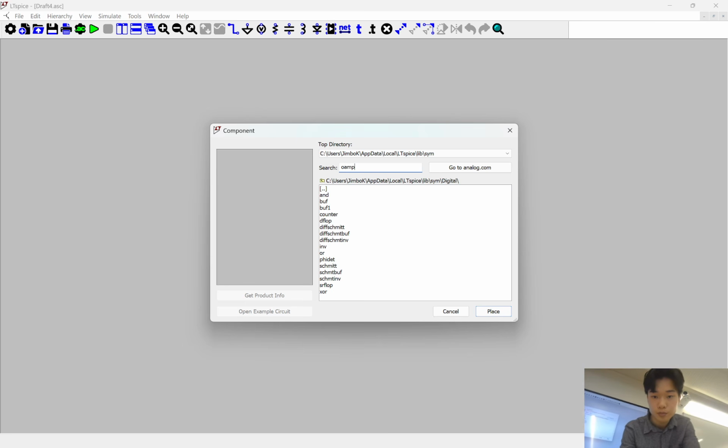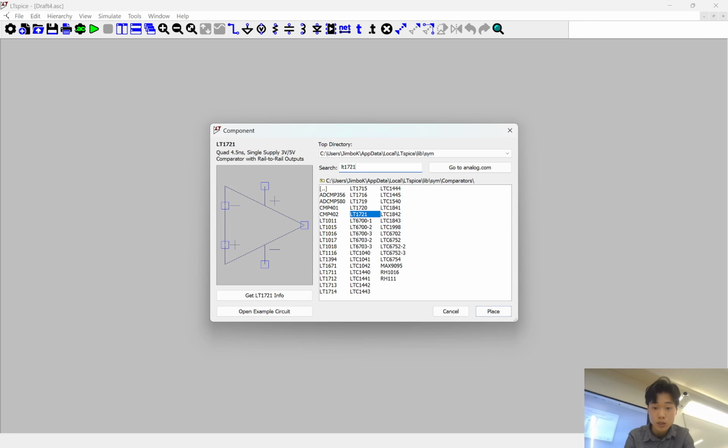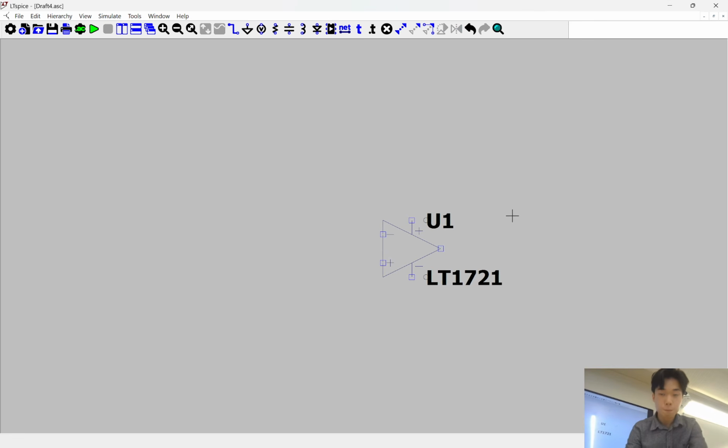So in the notes, we've listed LT1721, right? It's just some op-amp model. I guess it just depends on the application, right? Because if your intent is to simulate a circuit that you're going to use in real life, then you would generally prefer to use the exact op-amp model because it'll include some of those imperfections as well.